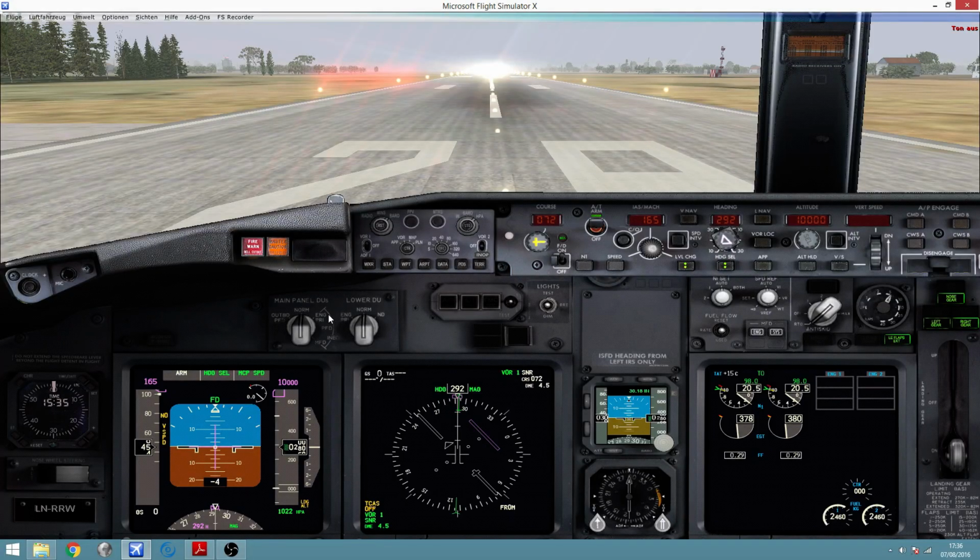We were on the navaids row. Course and heading selectors are according to the SID. Yes, they are. So course is 072 and the heading is the runway heading all the way up to flight level 100. Level change on green, selected cleared altitude, flight level 100, and it says transponder, code entered, and TARA. How do I do that?